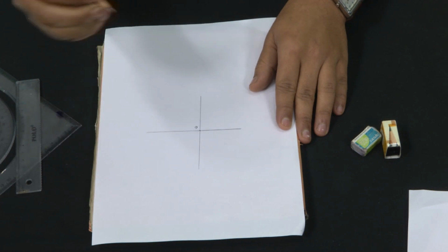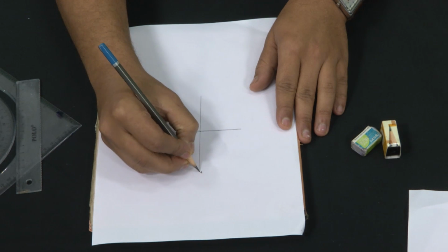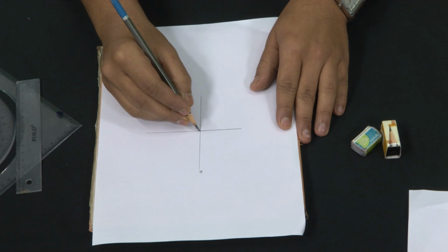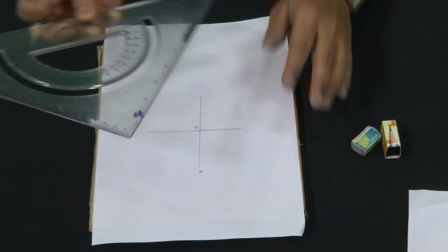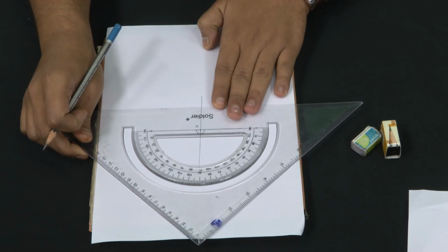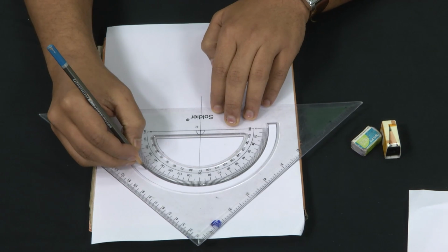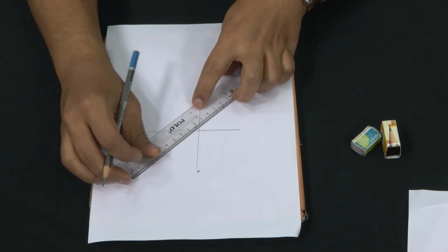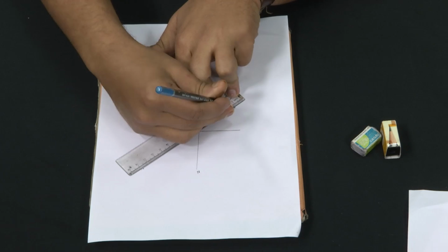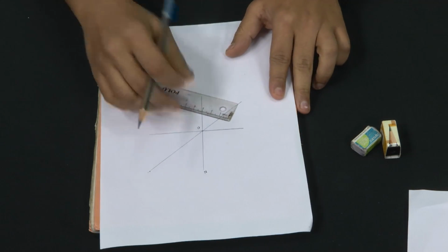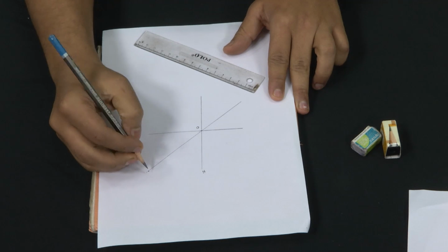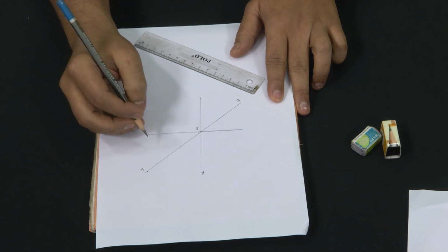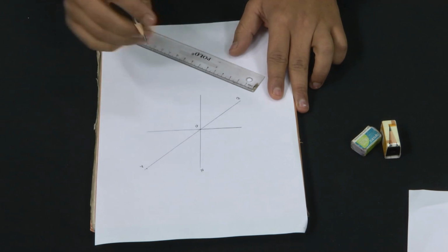Clearly, we have to fix the north. Conventionally, we fix the north as the top of this line. Now, we will measure 50° from north towards east. We obtain a point and then we join this point with the origin. So, we will consider this line, suppose I name this line AB passing through the origin, as the 0 meter strike line or stratum contour of the bed.